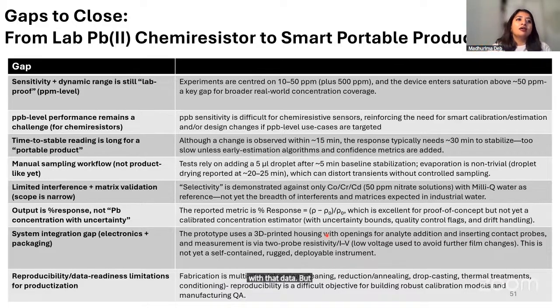But I waited for my own sensor to stabilize because it was a lab based sensor first. I waited for 30 minutes, stabilized the result, checked the standard deviation for 3 results, and then reported the results. We can utilize this kind of data to make it smarter with the help of better calibration.